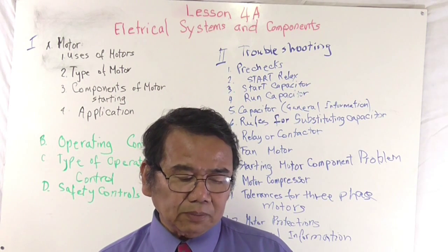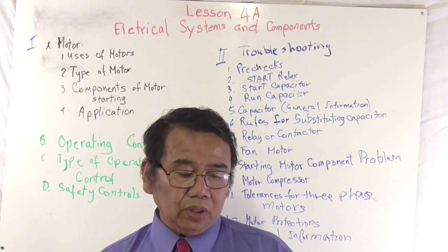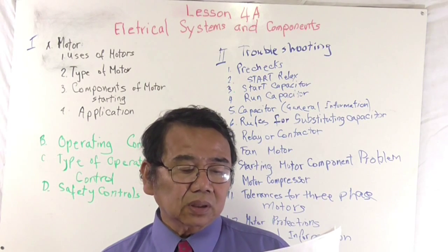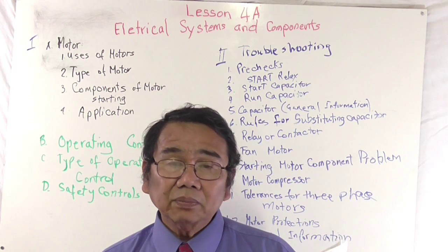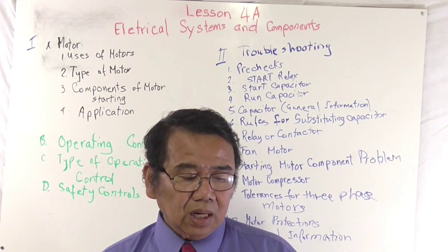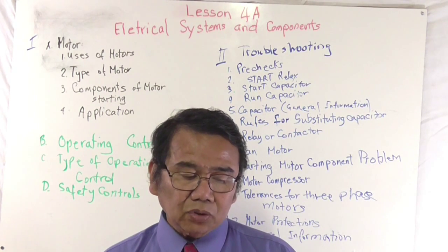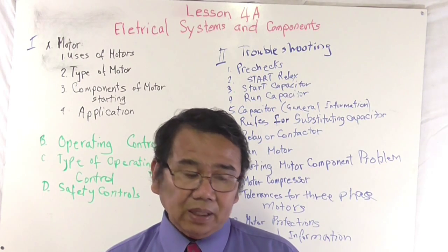What are the rules for substituting capacitors? Substituting capacitors, voltage: for either capacitor, the voltage must be equal to or higher than the one being replaced. Run capacitor: the capacitance value cannot exceed plus or minus 10% of the one being replaced.